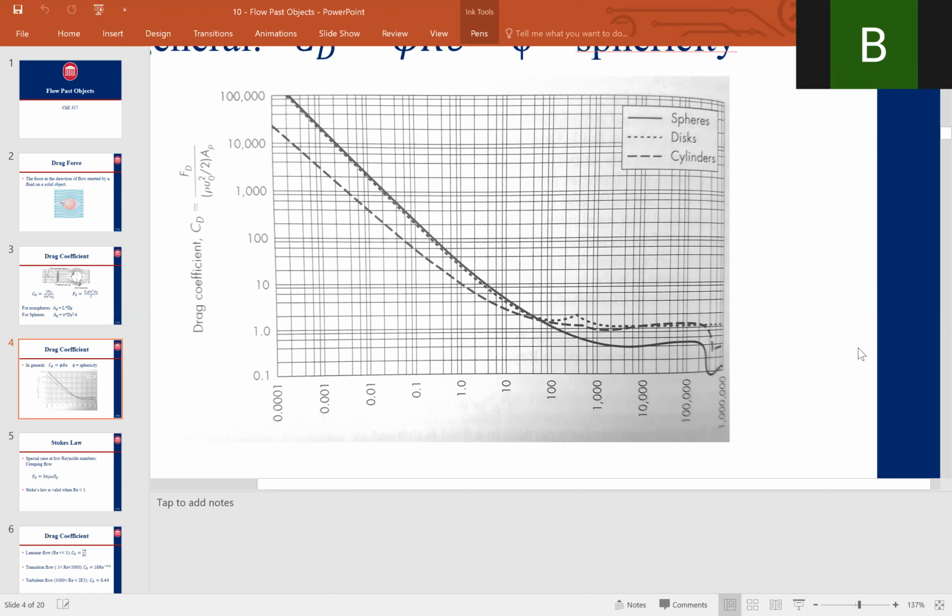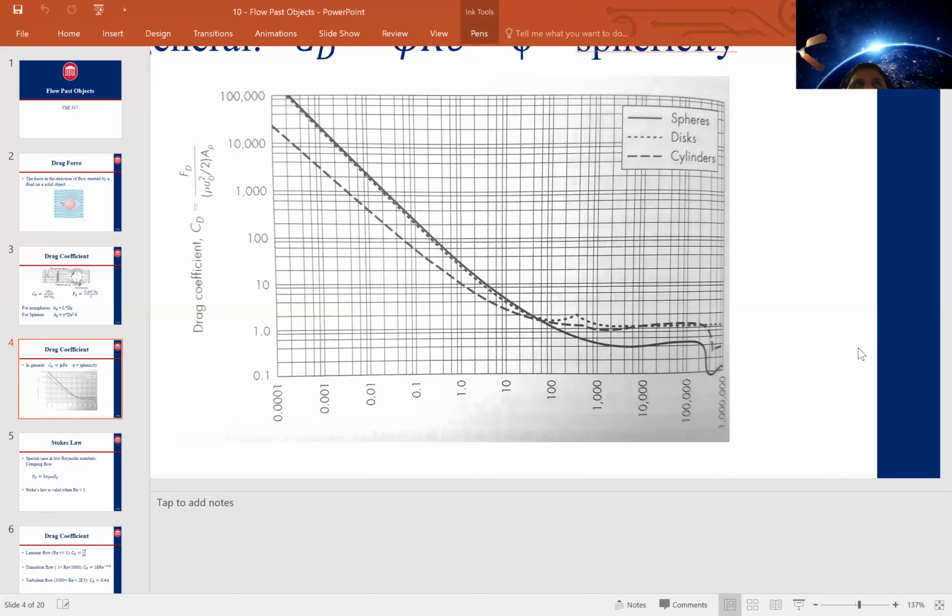Yeah, I guess it's just like a rule of thumb, like at what value you would say you really need to go in and correct. Oh, in terms of making an assumption, even if it's not an ideal sphere? Yeah. That's a fair point. Anything I would say below a sphericity of about 0.9, you would definitely want to correct. But if it's 0.9 and above, this might get you a solution with reasonable accuracy.